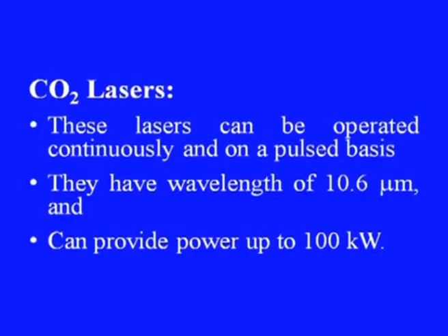They have a wavelength of 10.6 micrometer and they can provide power up to 100 kilowatt. That is why they are preferred in most industrial applications where high power is required. The carbon dioxide laser is the most powerful among all lasers and is primarily used for cutting and profiling.